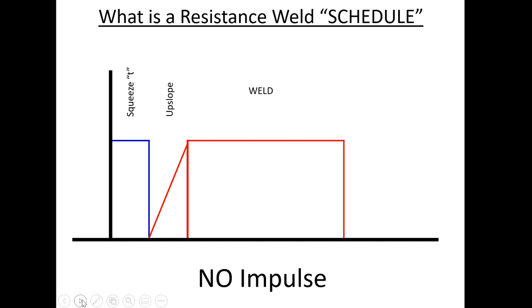Then, of course, we have our weld. Actually, our weld schedules are relatively easy. There's a million different charts out there to say this thickness to this thickness should be this temperature. But always keep in mind, when you're talking about current, it's relative to the amount of force.